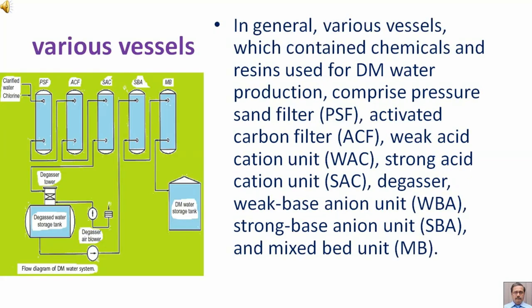In general, various vessels which contained chemicals and resins used for DM water production comprise pressure sand filter PSF, activated carbon filter ACF, weak acid cation unit WAC, strong acid cation unit SAC, degasser, weak base anion unit WBA, strong base anion unit SBA, and mixed bed unit MB.